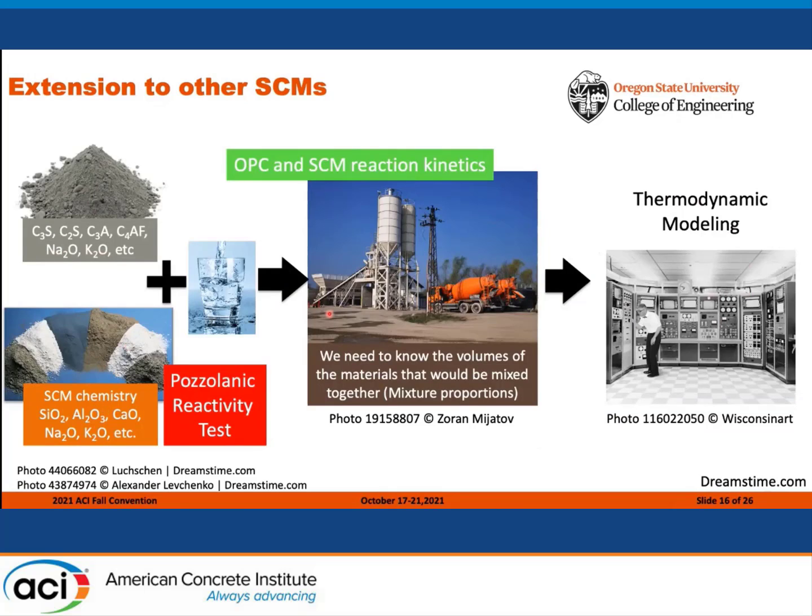However, this process is not trivial. One complicating factor is the pozzolanic reactivity of the SCMs, which is a key parameter that tells how much of the SCM is available to react. Also, the PK model is specifically developed for the OPC clinker phases and does not cover SCM oxides.